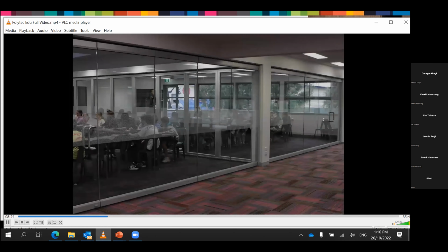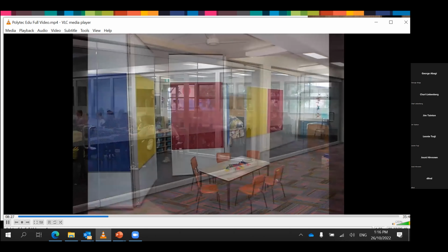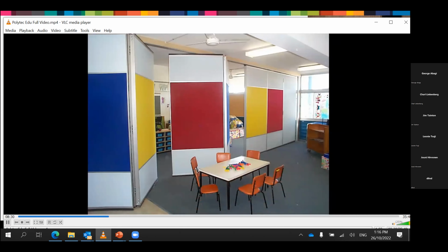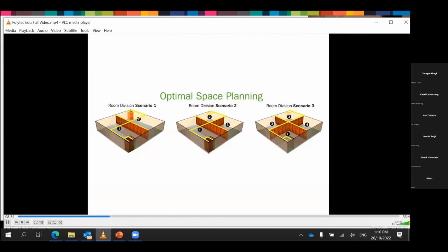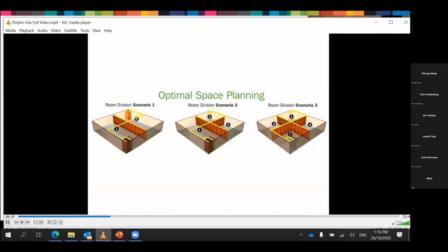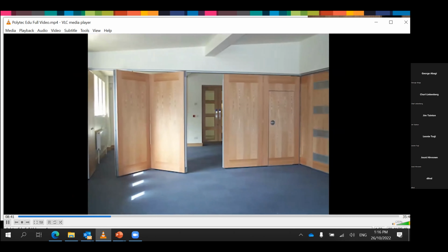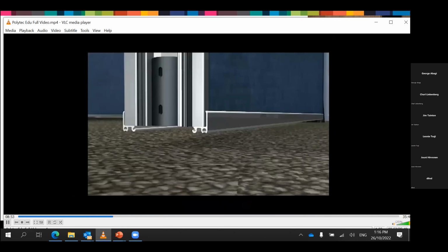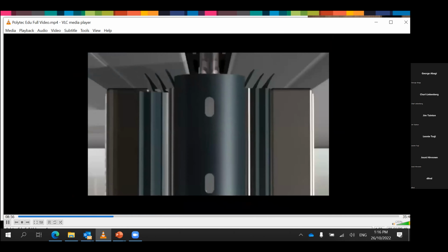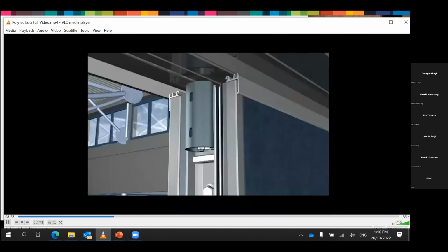As education facilities evolve into more flexible spaces, operable walls and sliding doors are more frequently specified, which will be discussed in more depth in Objective 2. An operable wall divides available space, enabling flexibility, while sound-rated panels still allow for effective noise control. When sound waves strike a partition, some are reflected from the surface, staying in the same room as the source of the sound. Some are absorbed by the material of the partition, being converted to heat energy, and some are transmitted to the other side.